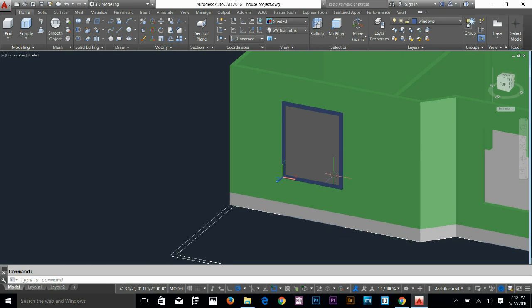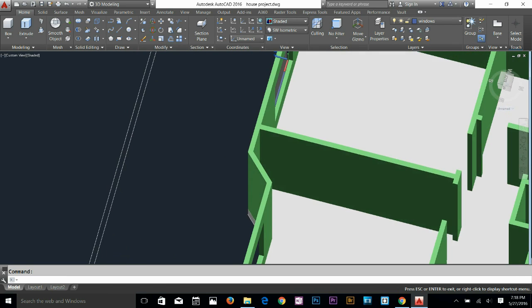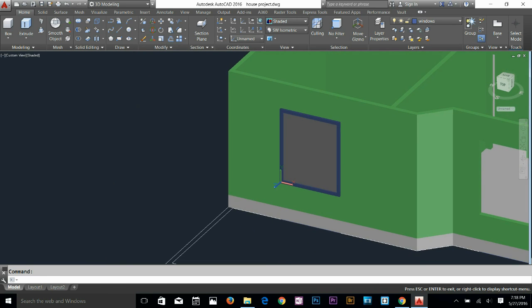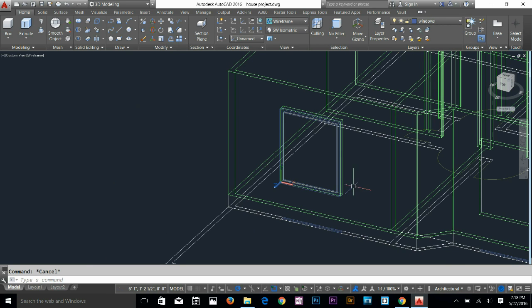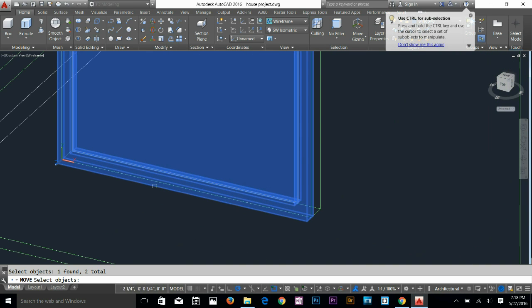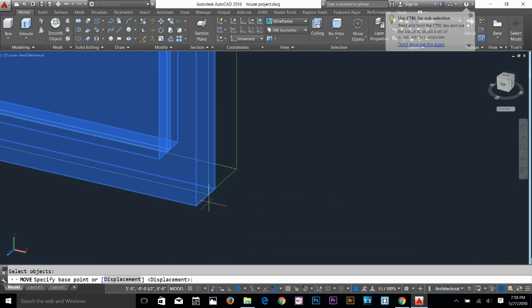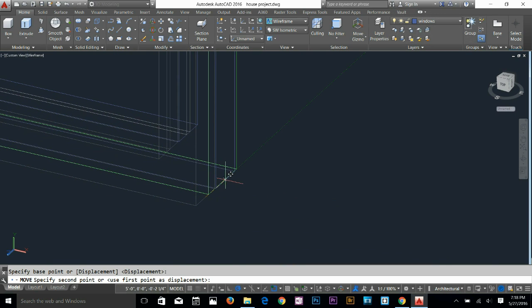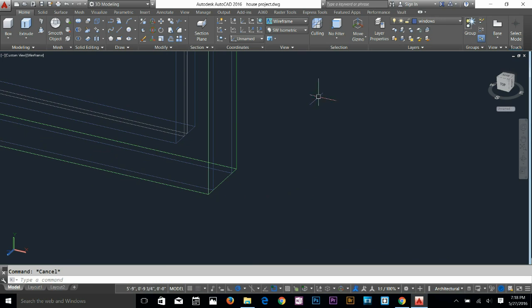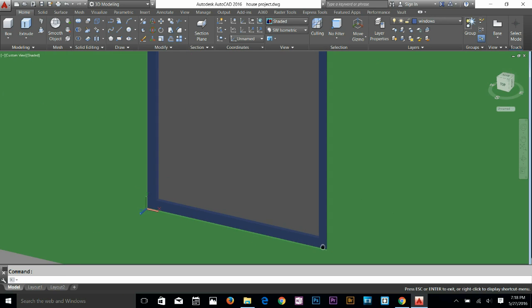Done. Okay, alright, so we got our window coming out actually. So what I can do, just gonna change that to shaded. You could give the values, but I just wanna select my glass and window layer, and I want to basically select it from midpoint and just drop it to this midpoint, right? Okay, so let's find out now. I'm gonna go to shaded now. Well, this is perfectly fine now.